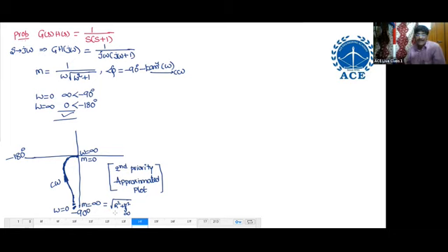It is correct only according to polar, but rectangular gives the exact point where it is starting. That's why we have to find the rectangular coordinates at omega equal to 0.